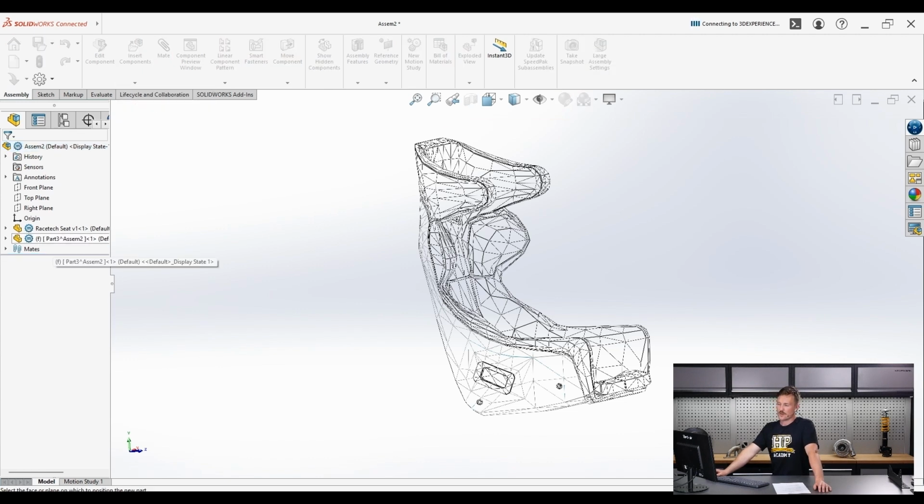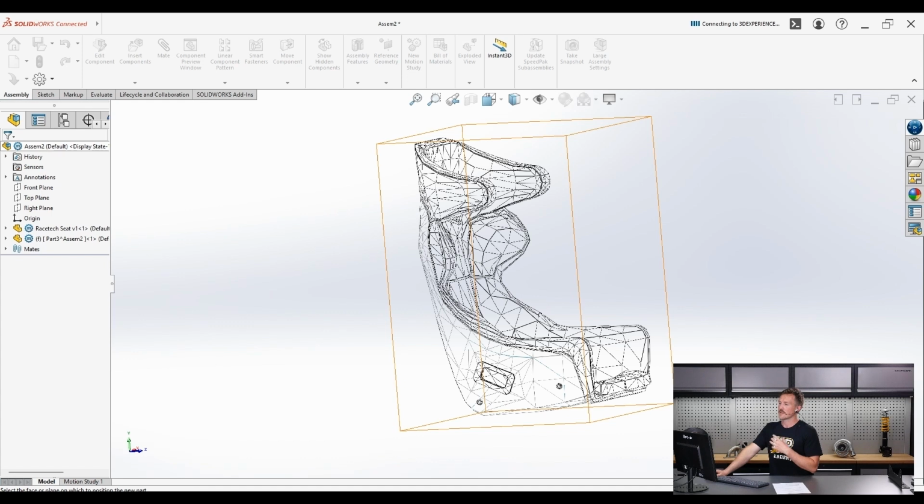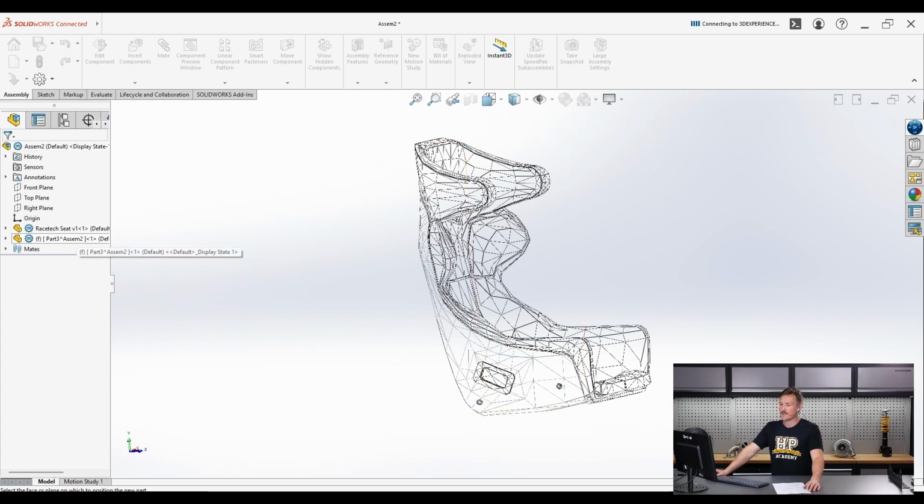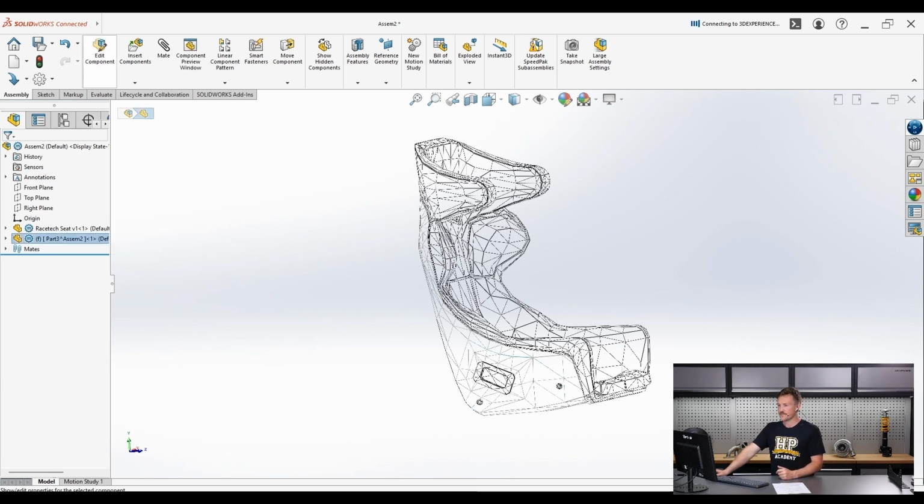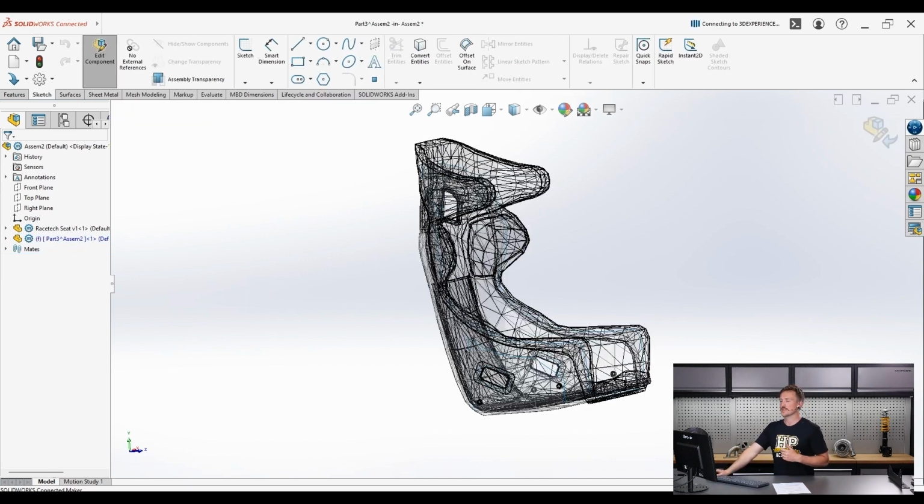And that's just going to create this new part here, which is fixed, and we can leave that fixed as well because it's fixed to the coordinate system of the model, which we want anyway, so there's no point doing that same method again. And we'll just click to confirm that, and then this is the difference here where we can jump into edit component. So if you're familiar with Fusion 360, this is just the same as doing an edit in place on an external component within an assembly file.